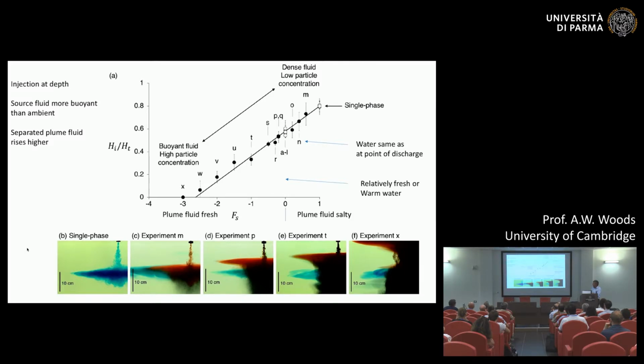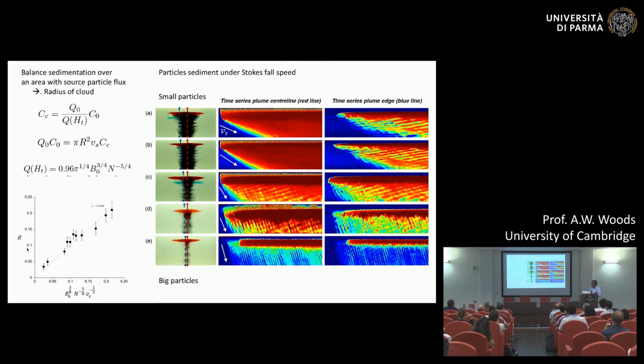And if we make the fluid very fresh, so even fresher than the surface water, so it's got a linear stratification, it will have a density up here somewhere, then what's going to happen is we're changing the total salt in that intrusion. And so by changing the salinity of the source fluid, we can actually change the height of the intrusion. And by making the source fluid sufficiently fresh, it's possible to get this intrusion even to occur on the surface of the water. Okay? So that might be one way of trying to manage it, and then I'm trying to recover that material.